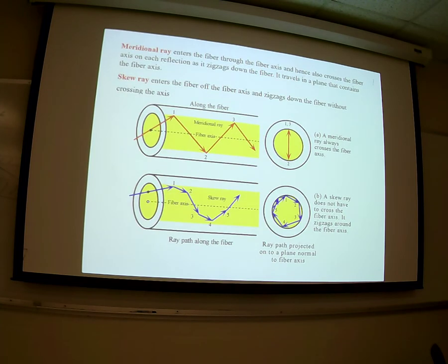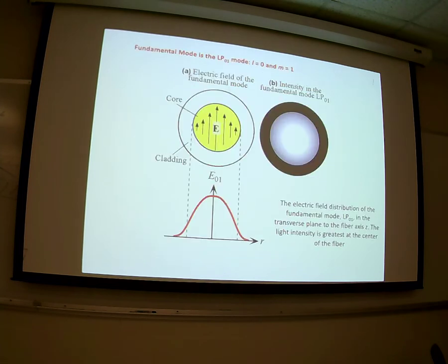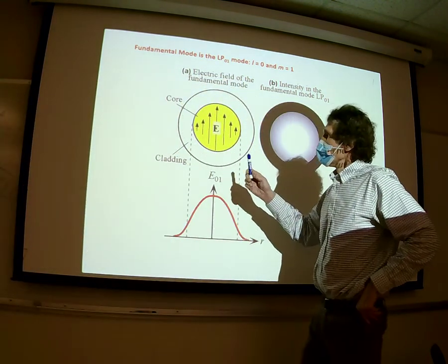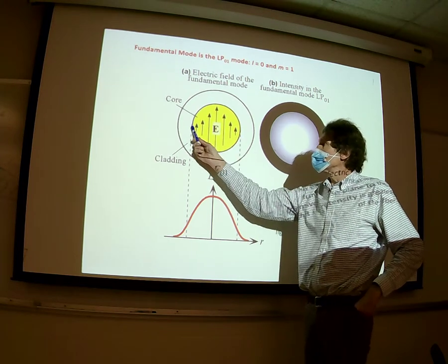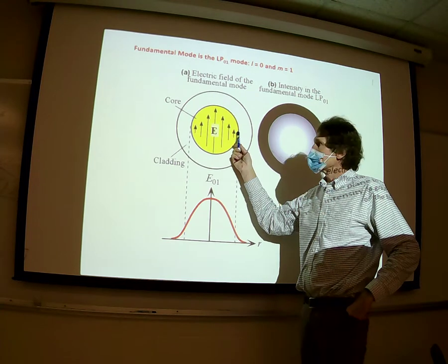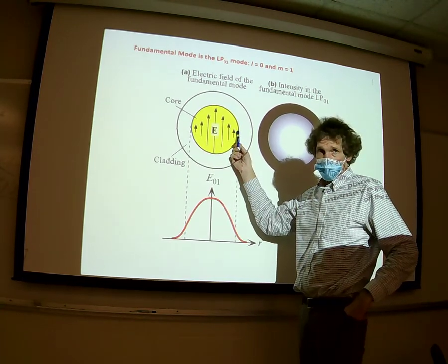All right, so here's the standard thing. Now, the difference with these things, I want to tell you this much. Here's showing you one mode of fiber optic, the fundamental. Actually, fundamental is one mode. All right, the solution across here is about a half wavelength. But it's not a cosine variation, it's a Bessel function variation when you solve the del squared equation.